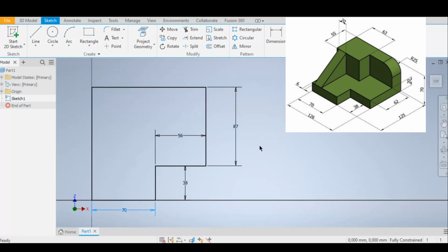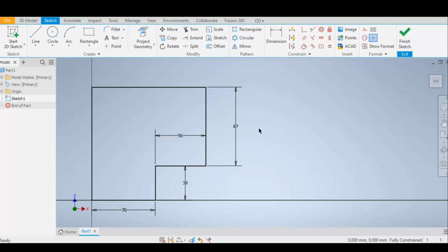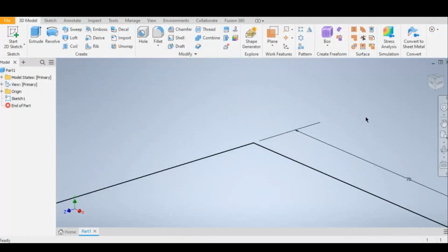And if you want to edit any of your dimensions on the sketch, you can simply double click a dimension, and you can see for this dimension we actually used a little formula here. But if you have noticed that this is incorrect, you can edit your dimension from this. So it's quite easy. It's a great way that you can start to work in Inventor. And this is now our base drawing. So to get this done, I'm simply going to click on Finish Sketch at the right top corner, and you see that our first section of this is done.